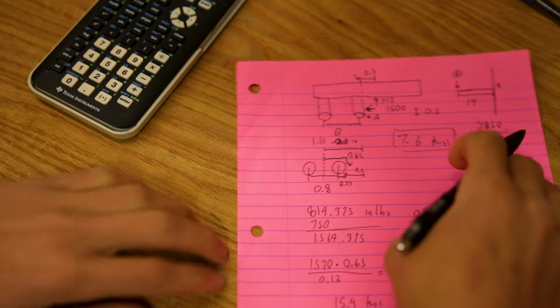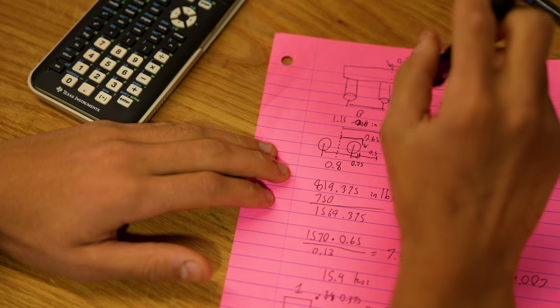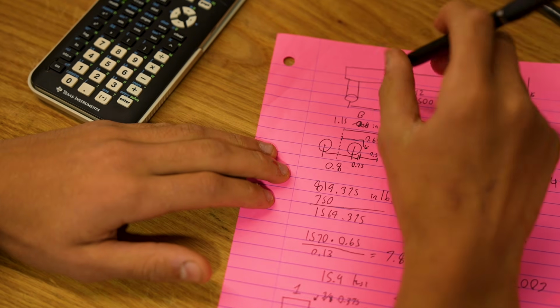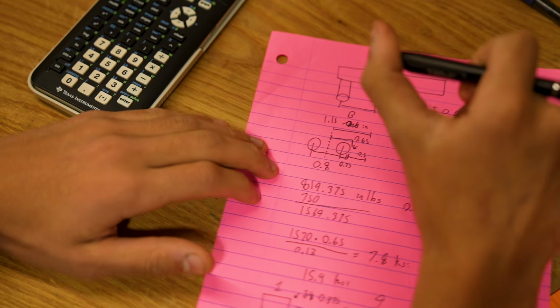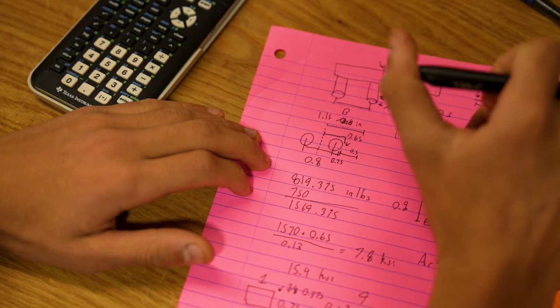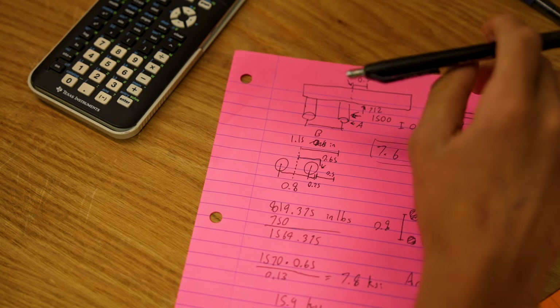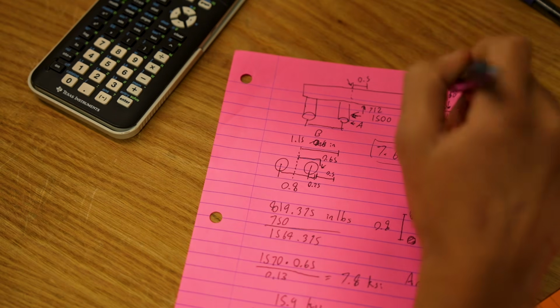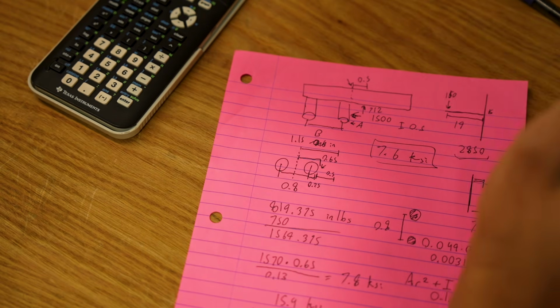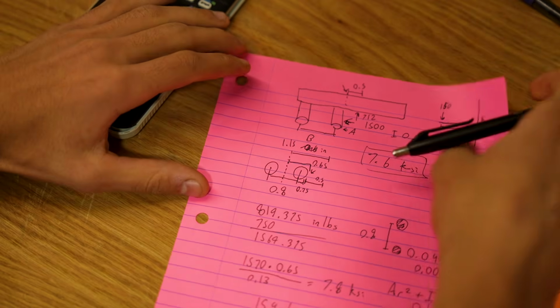What do you say typical safety factor we're targeting is? I feel like 3 is pretty safe. Yeah. 2 is a little. I mean, the only thing that was under 2 is our chain, and that's what snaps first. So it's hard to say what our other stuff is going to snap. It would have been great to push this to failure, which we may, but we might do that right after our Michigan little event.